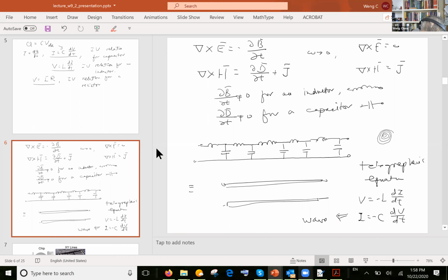So they make wires like this, and then you will have a connector. So this essentially is what a spiral inductor is. And when current passes through this structure, it generates a very strong magnetic field B. Because it generates a very strong magnetic field B, it stores magnetic field energy and it behaves like an inductor.